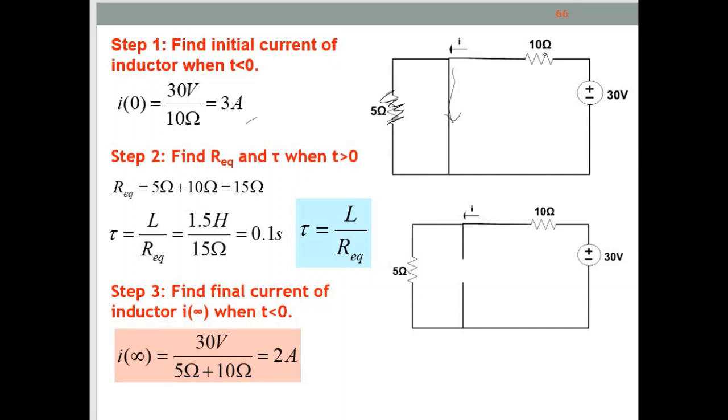Next is the I infinity. Okay, similar to the circuit of source transformations. I infinity here, because this is open circuit, don't consider this line, just 10 and 5. So straightforward, whatever flows through 10 ohm will flow at 5 ohm.